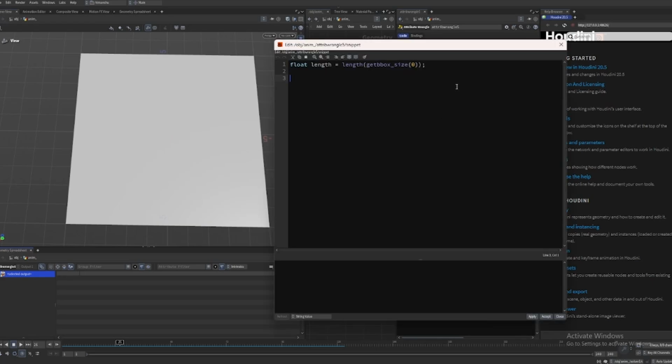So let me just do an integer handle is equal to pcopen 1, @P, the distance, which will be our length, and pt will be 1, let's say. Okay, then we can have a vector position is equal to pcvex, the handle, and let's say @P position.